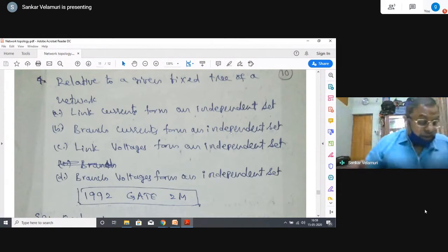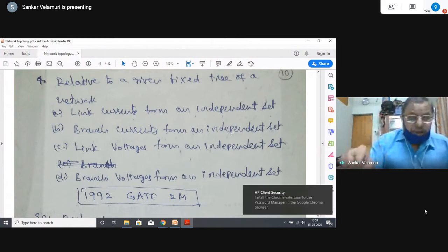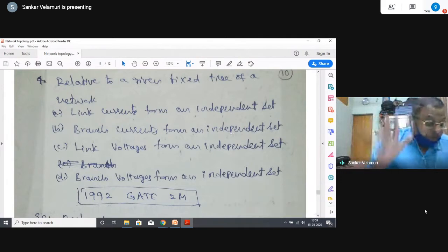So why is the graph method used for electric circuits? It is not that electric circuit theory takes it as the basis of solving problems. It is not a method. Graph theory is only a solution strategy for how many equations to solve, depending on the number of loop or node equations. You said A into A transpose. Yes, it is correct. The number of trees can be obtained. Somebody has asked. The determinant of A into A transpose is correct.